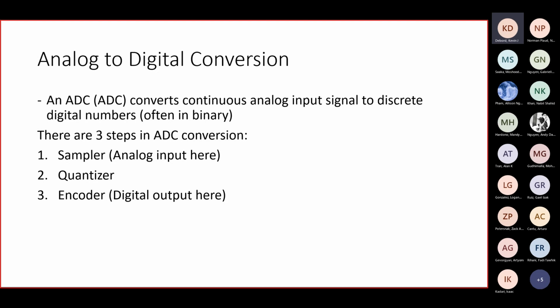Go for it. Over the course of time, a sampler has a certain clock speed or sample rate. The sampler will take snapshots of what the voltage is at that time. I like what you said there, but simplify it for me. What axis is it turning into discrete values? What axis is time normally? Yeah, the x-axis, right? The quantizer, what axis does that turn into discrete values?